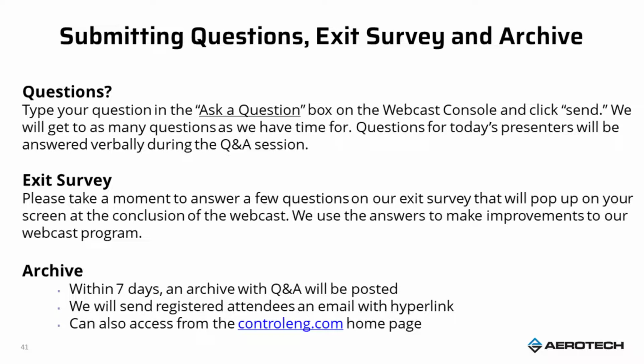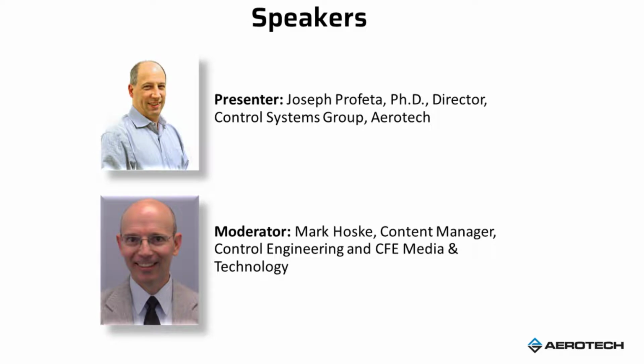That's a good question. So the first thing is, often when we're sitting in front of the controller and using the tools that it has, the digital nature of the controller is hidden to us, and so we'll measure a response and we see the real response and change the gain, and so at a basic level we don't really have to think about that very much. We can just change the gains and see the response of the system, and if it's good, it seems like it was a good choice, and if it gets worse, then go back to where you were.